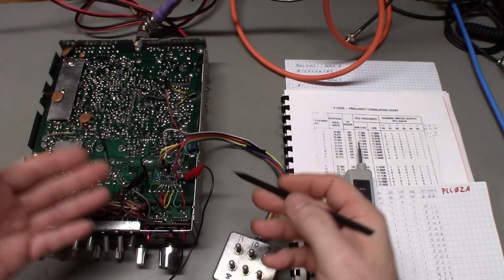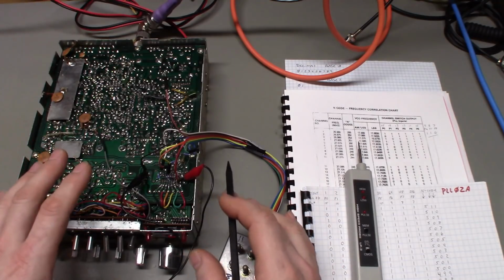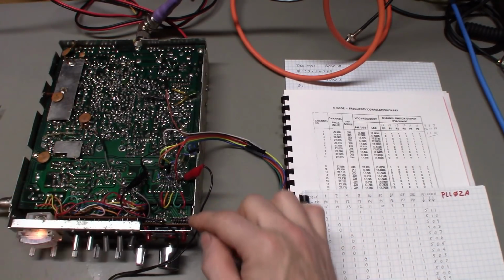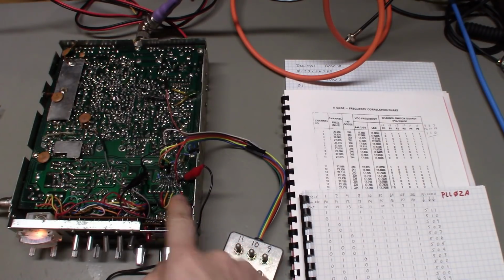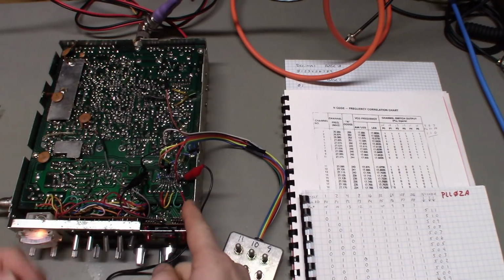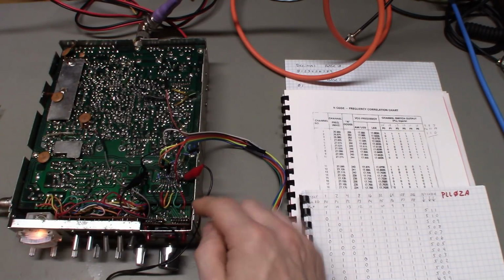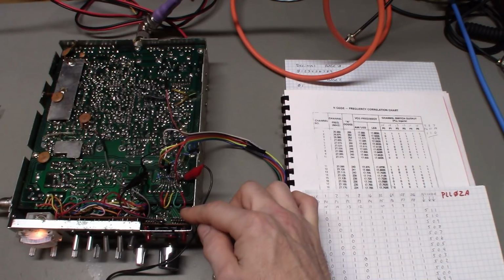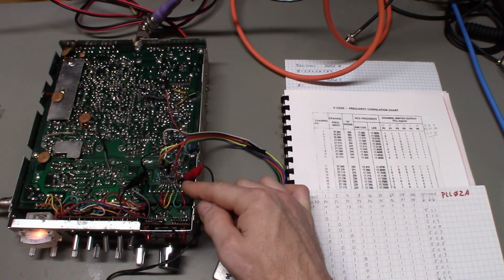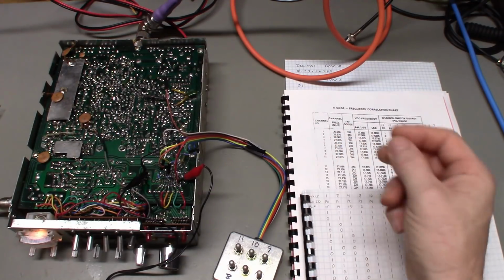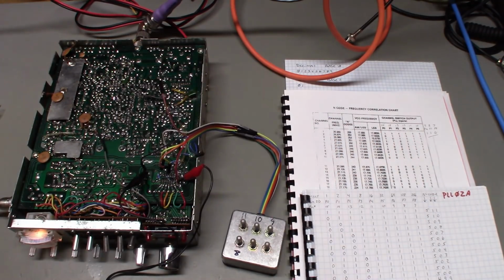Now when you do modifications, all you're doing is, when you want to get extra channels, you need to intercept basically the signal, which, remember, the signal is nothing more than either a ground or a voltage being applied to those pins. But you need to intercept that, what's coming basically out of the channel selector, before it gets to the PLL, and then you can apply either your ground or your voltage source. And that's what I do with this little box.